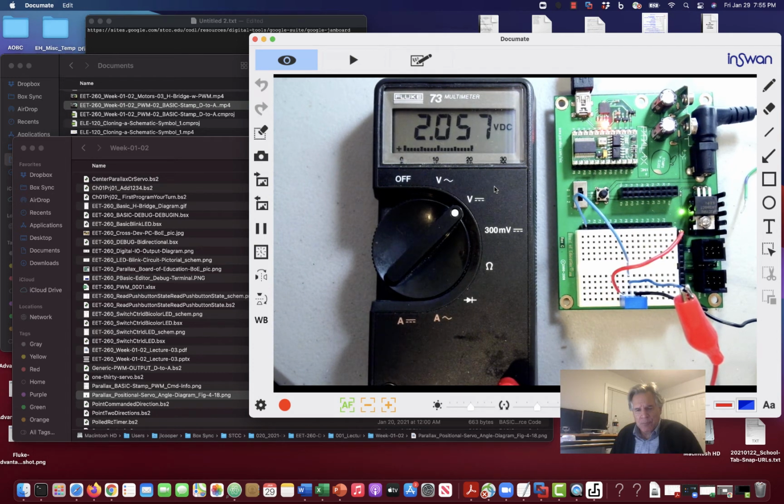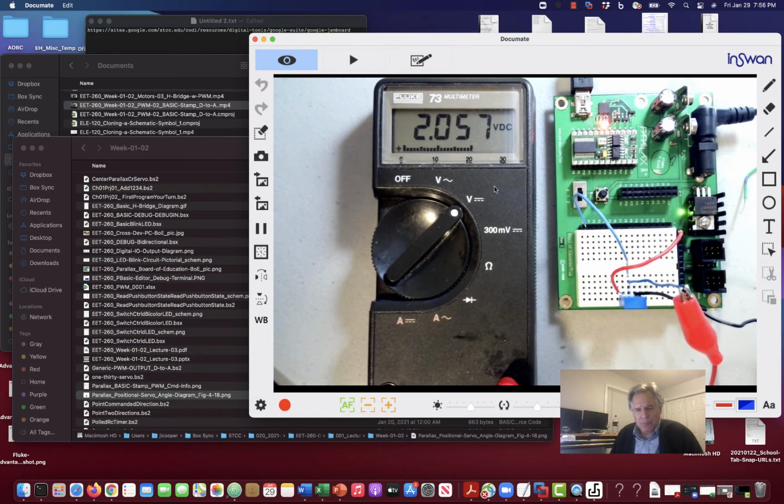Some of those are CMOS and some of those are bipolar TTL. The TTL ones tend to have that 0.8 volt max input. Sometimes it's 0.4 volts, depending which family it is. And the minimum high voltage is a 2.4 volt input, sometimes 2.0 volts. I think I was remembering that incorrectly. But regardless, between 0.4 and 2.0, you've got that dead band, and that gives you good noise immunity.